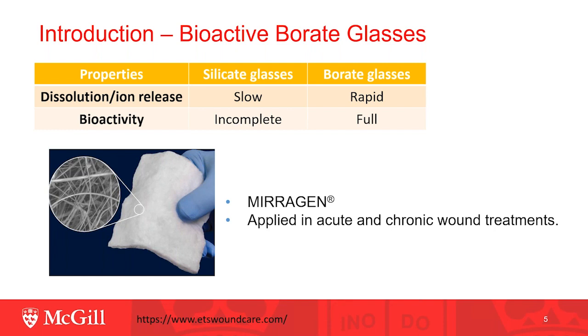Due to the structure difference, the borate glasses have lower chemical durability and higher dissolution and bioactivity than the silicate glasses. Therefore, borate glasses have a greater advantage in mineral tissue regeneration and in wound healing. One borate glass has obtained FDA clearance as a wound dressing. The properties of borate glasses are much dependent on their structure, so the structural features of borate glasses will be reviewed first.